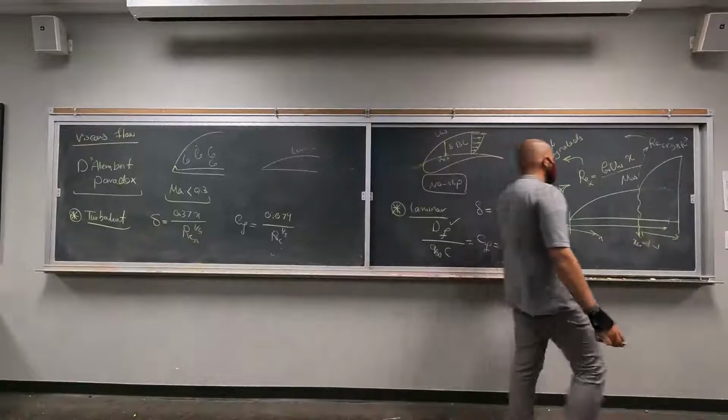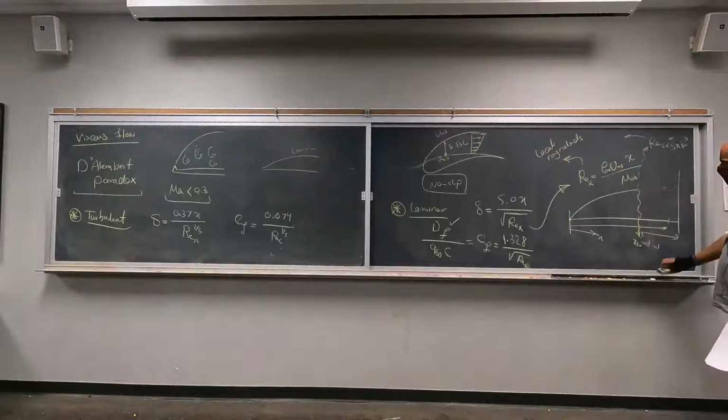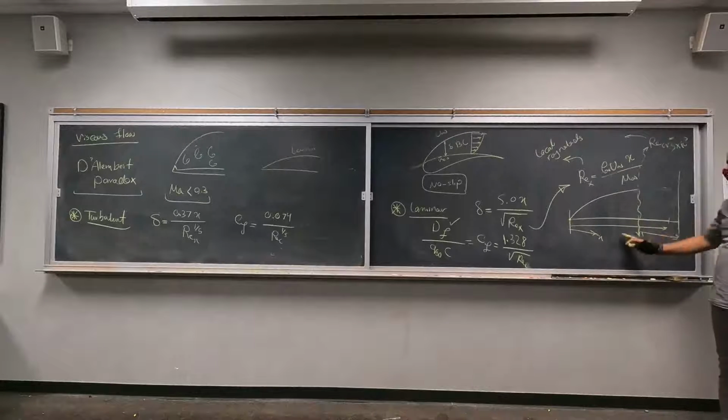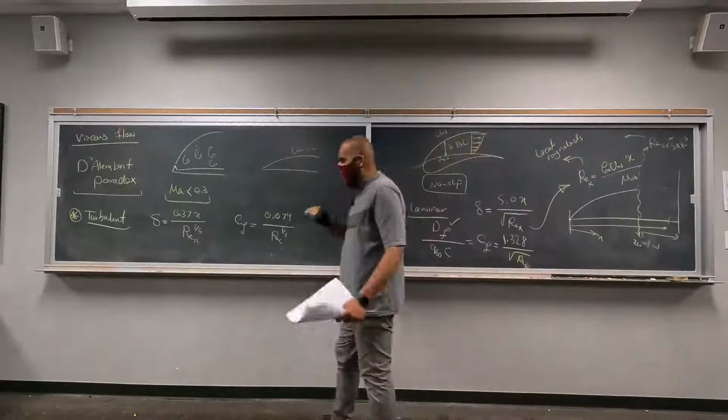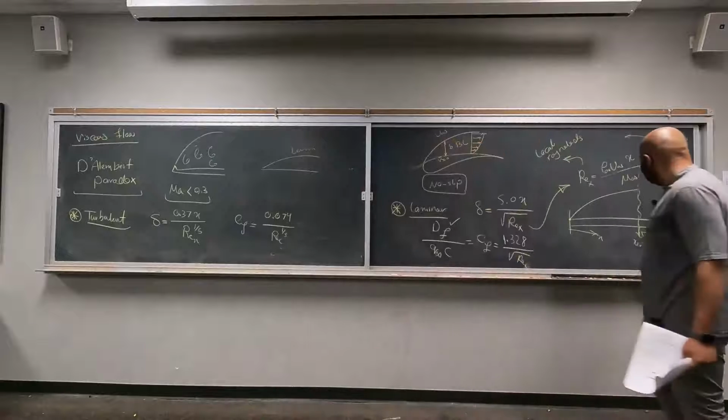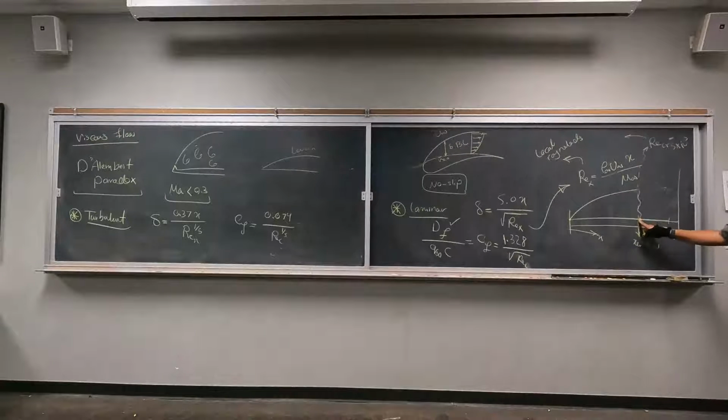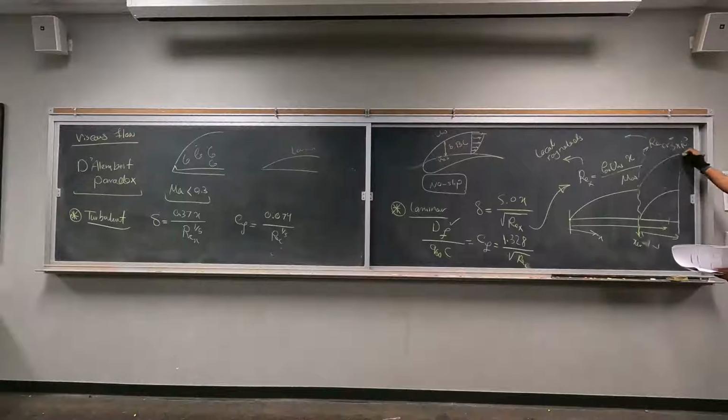The reason is the first part, for the laminar part, you're correct, right? You can just plug in the values. But this equation gives us a friction coefficient where the boundary layer starts with 0 thickness. So if we do what you're telling us to do, we're essentially assuming that we have a laminar boundary layer until a transition point, then the thickness goes to 0, and we start back with a turbulent boundary layer, right? So this solution doesn't apply because we are removing all of this part of the boundary layer.